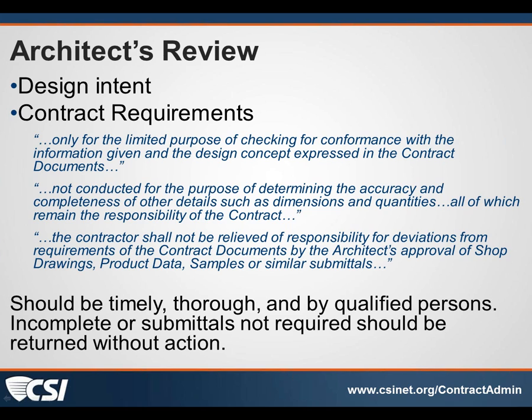And again, as Jim said, it's a part of that teaming that can value a lot and go a long way. Right. So we talked about what the contractor's review is for. This slide talks about what the architect's review is for. And you can see the language there per the AIA general conditions. It's the limited purpose of checking for conformance with the information given in the design concept expressed in the contract documents. So we are looking for design intent. We are not reviewing them to determine the accuracy and completeness of other details such as dimensions and quantities, all of which remains the responsibility of the contractor.